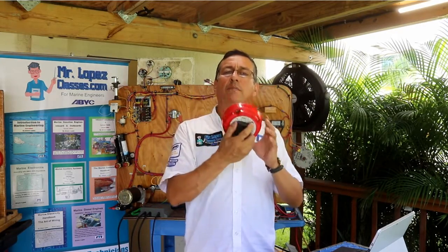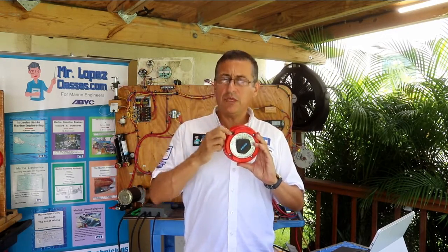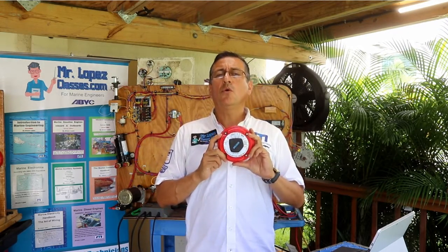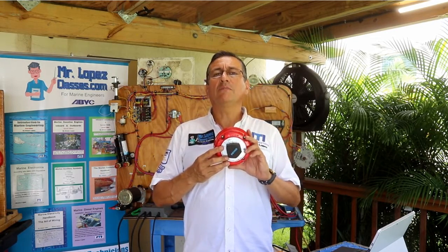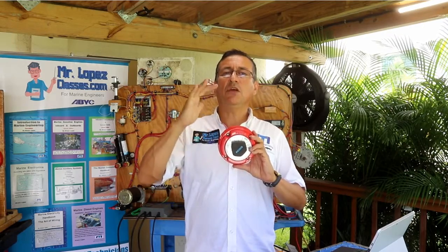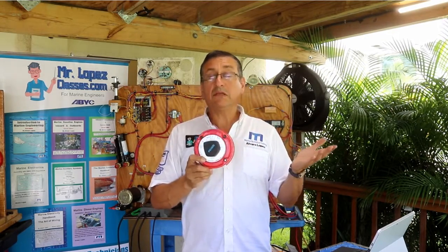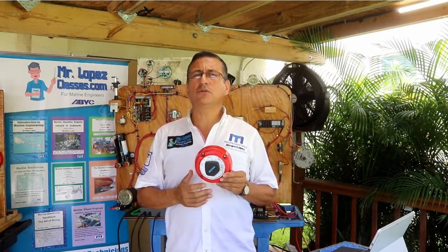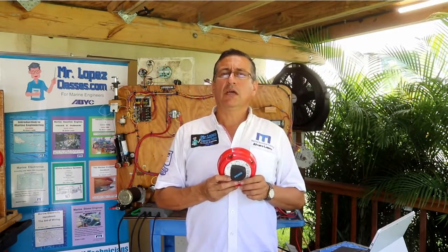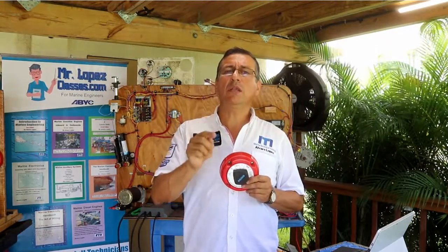Yeah, the enemy of the battery switch selector is the temperature. The temperature increases inside of the battery switch selector when the amps increase, when the amount of amps is superior to the capacity of this device. This is basically the theory of battery switch selectors. There are a lot of manufacturers for battery switch selectors. You can select any of those manufacturers if the manufacturer is marine approved.